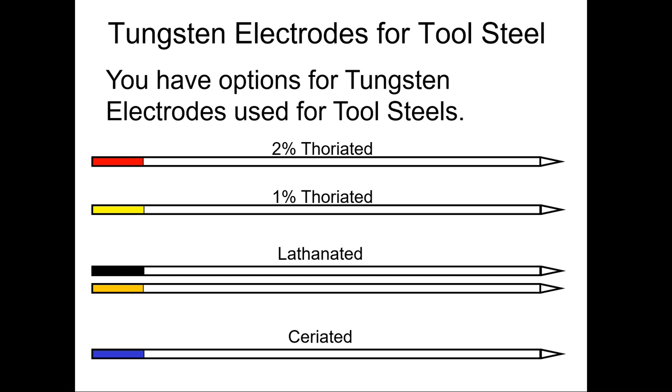And while I'm on this topic, and this is super, super important, we do not use tungsten carbide grinding wheels to sharpen tungstens. These tungstens are not tungsten carbide. There's no carbon in them at all. It's just tungsten. They're not even hard. If you put a sharp point on it, you can put it down on a piece of plate and wear that point off quick because there's no carbon. So keep in mind that these are not hard. Okay?